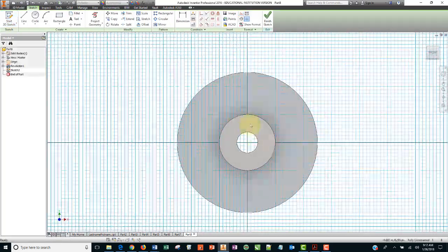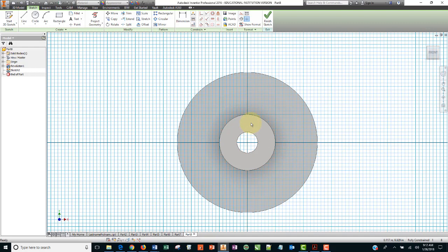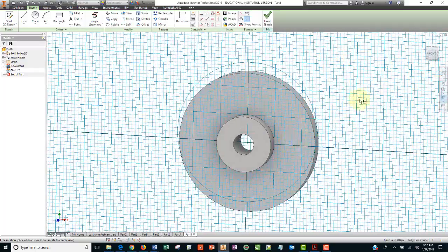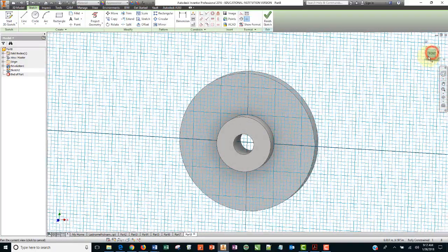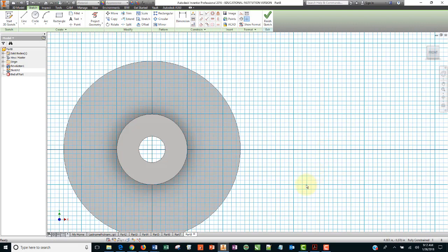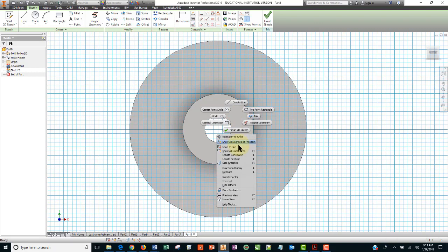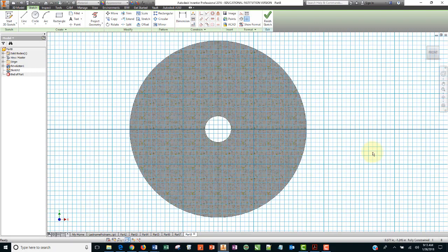and here's another new technique I don't think we've looked at. If you right click on stuff that is above your sketch plane, so as you can see here, I've got this piece above the sketch plane, and it's not really in the way, but you will in the future have problems where you've got stuff in the way of your sketch plane. The way to get rid of that is to right click, slice graphics, and it goes away.